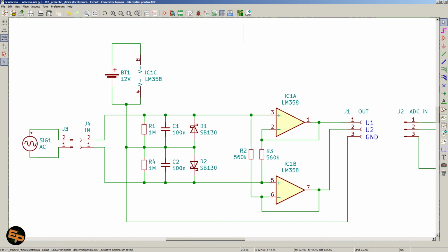Also, this circuit is necessary even if we have only positive voltages that we want to send to the ADC, but those voltages are not both referred to the ground, but they are two voltages that exist in two completely different places in the circuit. In that particular case, we do need to measure them through such a circuit, because otherwise we will have a short circuit if we try to forcibly create a ground somewhere.